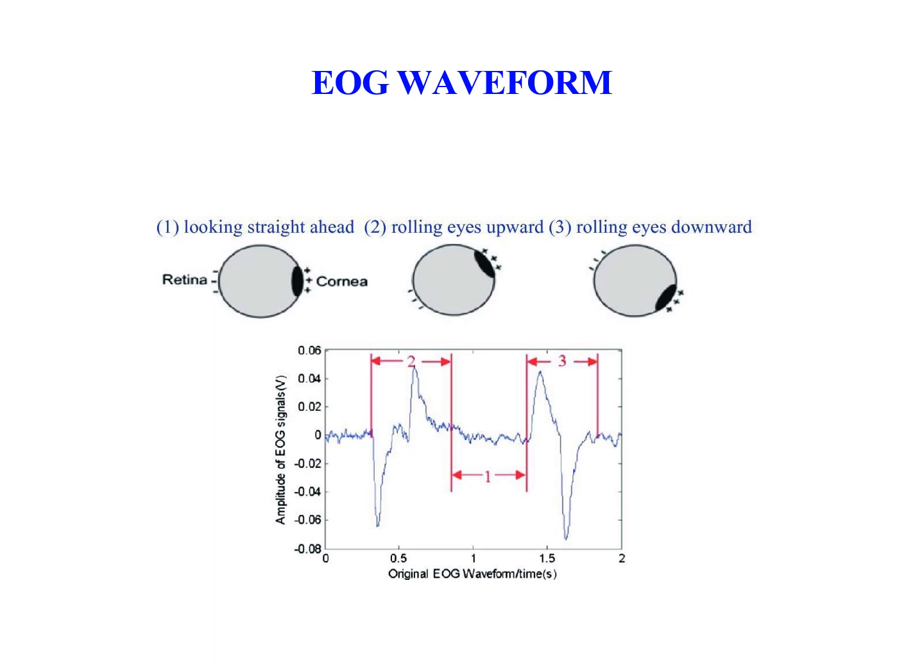These three diagrams are used to measure the electrooculogram waveform. The x-axis is time in milliseconds and the y-axis is the EOG signal amplitude. When looking straight ahead, the amplitude and frequency levels are very low compared to the second and third diagrams. When rolling the eyes upward and downward, the amplitude level changes up and down. The amplitude and frequency levels change in the EOG waveform.